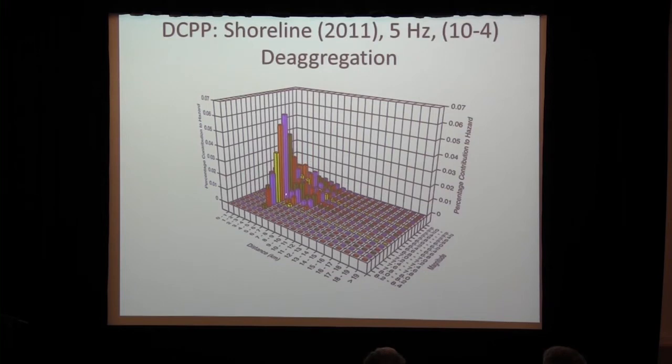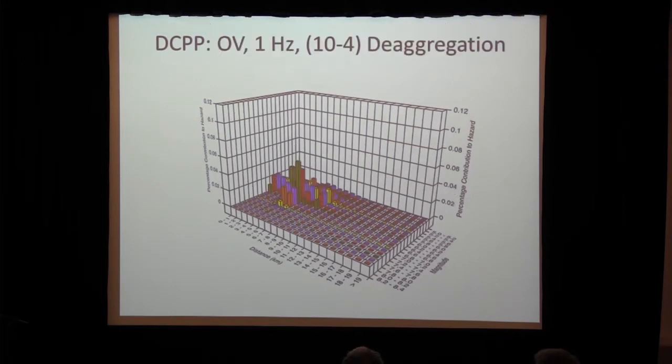And this is what I was talking about in the sense that the shoreline had 1 single trace of the Hosgri fault, so everything's going to be at the same distance. Whereas in the other case, you've got a little bit of a distribution on the distance. But as Norm showed this morning, as we look at the attenuation curves, whether you're at 4.6 kilometers or 5.2 or 6.1, those attenuation curves are fairly saturated, they're fairly flat. And so the overall hazard doesn't necessarily change that much, but the distribution and the contribution might be a little bit different between the source models.